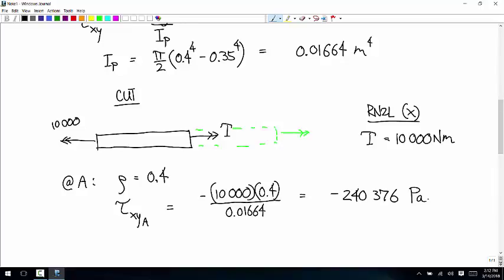That's such a gigantic internal torque and such a small stress. It's not going to break with that. You would think so with that torque, but then you look at this and that's tiny. No metal is going to break with a stress like that. The reason is that's a huge radius that I gave it.